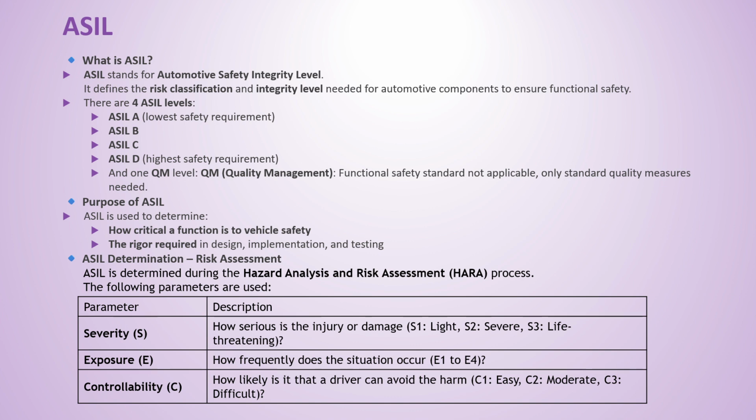There's also QM, quality management. That's for things where a malfunction doesn't really cause direct physical harm, so standard quality processes are enough. You don't need the full functional safety treatment. Think maybe the infotainment system map freezing, annoying, but not directly hazardous in the same way brake failure is.